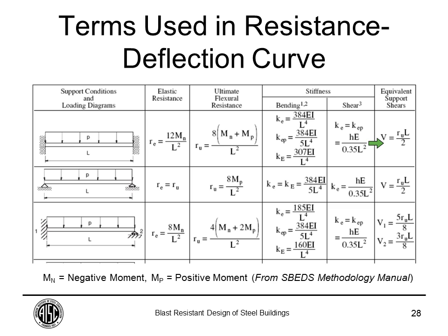Something that I didn't show here was the transformation factors. By the principle of energy conservation, typically the work done by the external force, the energy stored in the component, and the strain energy of a component that is loaded by blast has to be in equilibrium. So you need to do energy equilibrium methods to make sure that the single degree of freedom system has an equivalent energy absorption as the actual response, and that is done by the application of load mass factors that get applied to the load and to the mass. But typically they're combined into one that is called the KLM factor, and that gets applied only to the mass. And we're going to see that here when we do the first example.